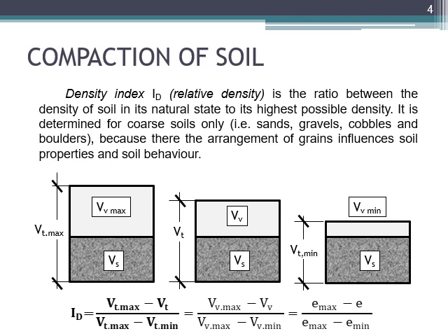If we already know the grain size distribution of the soil, which requires, for instance, the sieve analysis and hydrometer analysis if the soil is a mixture of coarser and finer particles, then we can usually give a name to the soil.